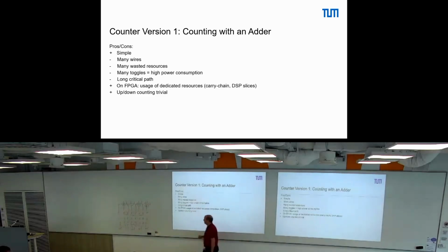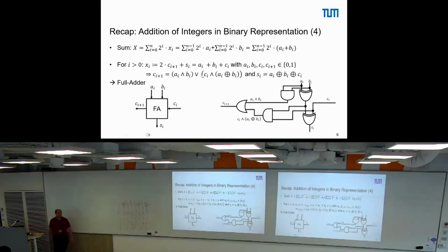So I go quickly to the ripple carry adder, just to show what I mean. This one here. If we only want to add always 1, we could fix one of the A's to 0 for most of the inputs, right?